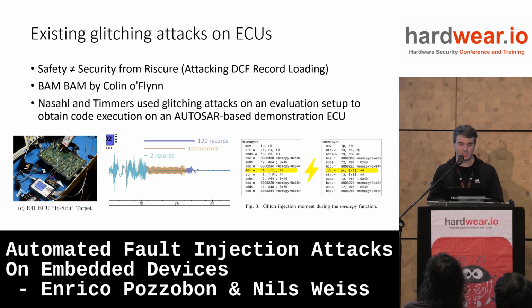Then we tried the BAM BAM attack by Colin O'Flynn, and unfortunately, this only works on the devices that have the BAM, boot assist module, but it doesn't work on later devices where the BAM was replaced with a different module. And our target was an example of one of these.